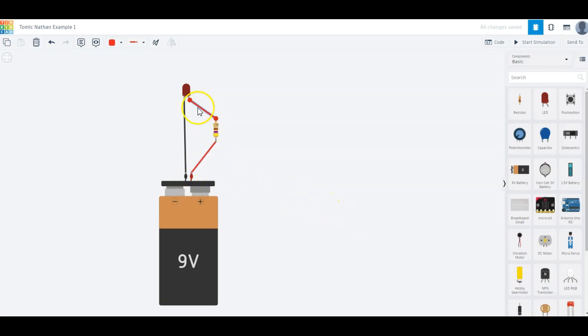I don't really like the way these wires are sitting like this. I'd like to make them sort of a little bit more straightish. And when I say straight, I mean actually putting a curve so that they sit nicely sort of like that. So to do that, I can either delete them, and when I draw a new one in, I can go from here across, clicking once there, and then come and join it up like that. Or if I've already got a wire, you can double click somewhere on that wire to add a node, and you can then bend it at that node. You can add as many nodes as you wish.